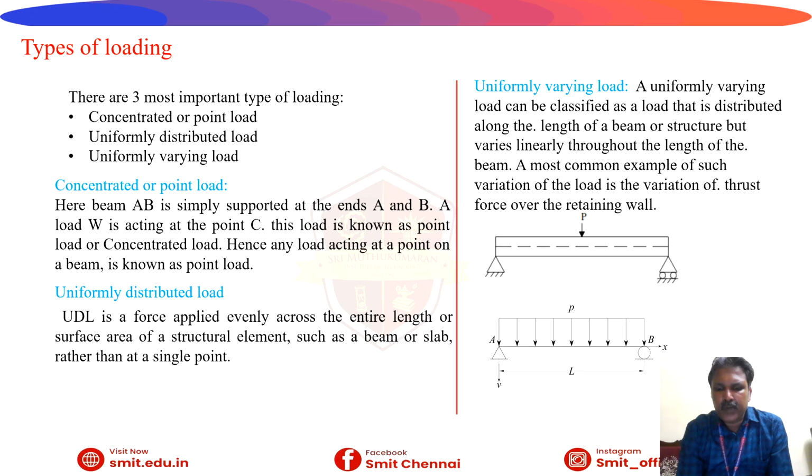It will be uniformly distributed. That is called UDL. UDL is a force applied evenly across the entire length or surface area of a structural element such as a beam or slab, rather than at a single point. Uniformly varying load can be classified as a load that is distributed along the length of the beam or structure but varies linearly throughout the length of the beam.